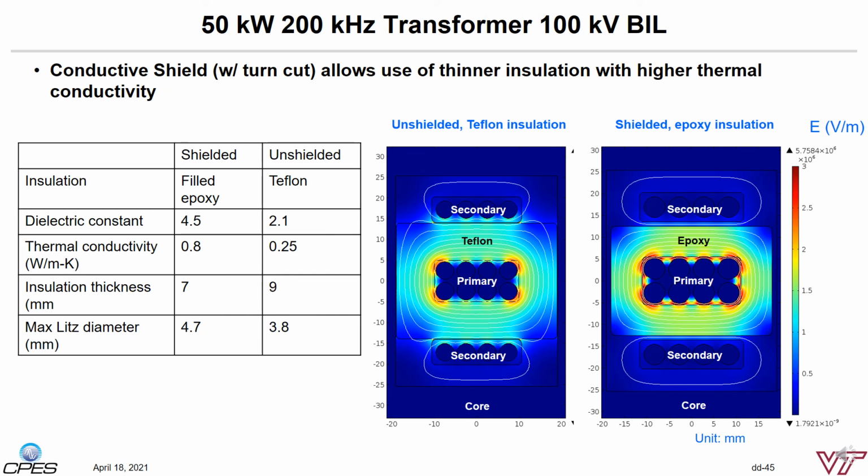This page shows the reason to apply the conductive shielding coating on the surface of the epoxy insulations. The shielding layer is connected to the low voltage side potential. Therefore, the voltage stress between 2 sides of the windings will be fully applied across the main insulation barrier, with smaller E-field spreading outside. In this case, we can effectively reduce the insulation barrier thickness, therefore improving the thermal conductivities and better electromagnetic couplings between the primary and the secondary side windings. Definitely, the conductivity of these shielding coating materials needs to be tuned to reduce the induced eddy current losses.